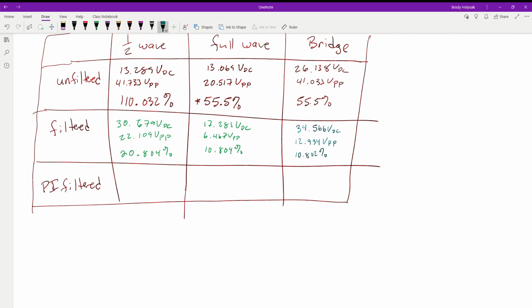Well, what you could do is you could take out your transformer. So now you could have, say a 1 to 4 transformer, instead of a 4 to 1. So what you do there is now you're stepping up the voltage 4 times. So instead of getting 42 volts out where you have 169 in, you could have 169 in and you could get almost 600 out. So it's really easy to kind of adjust these.